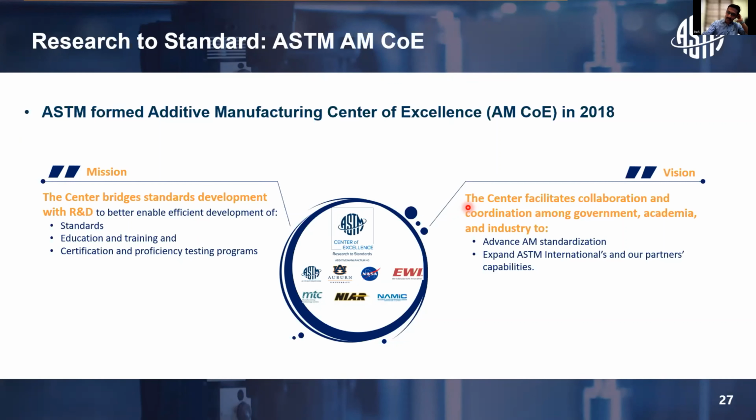Yeah, so the question is, how can we compare the data from tests conducted on parts from different machines? Obviously, one of the main issues with metal 3D printing is that when you use multiple machines, you cannot qualify parts printed from two different machines with the same qualification process. You'll be using the same qualification process, but you cannot say that the part made by machine 1 is similar to the part made by machine 2, unless you perform tests separately for these two machines.